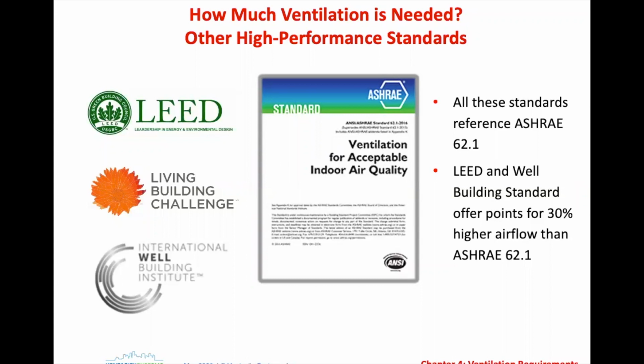One factor there, and I don't necessarily agree with this, and one of the ways I put it is better ventilation, not more ventilation. Simply doing more ventilation means you're using more energy. Even if you're using very high efficiency heat recovery to provide that ventilation, you're still going to have an energy penalty for the fans operating, and the whole system has to be designed to provide 30% more airflow. That's going to add both costs on the front side and operating costs. So I don't necessarily agree that just adding 30% is a good answer.